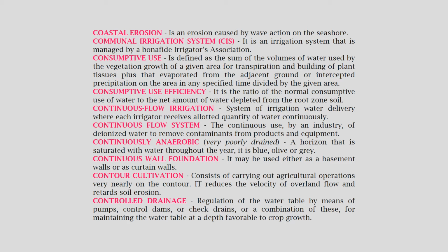Controlled drainage. Regulation of the water table by means of pumps, control dams, or check drains, or a combination of these, for maintaining the water table at a depth favorable to crop growth.